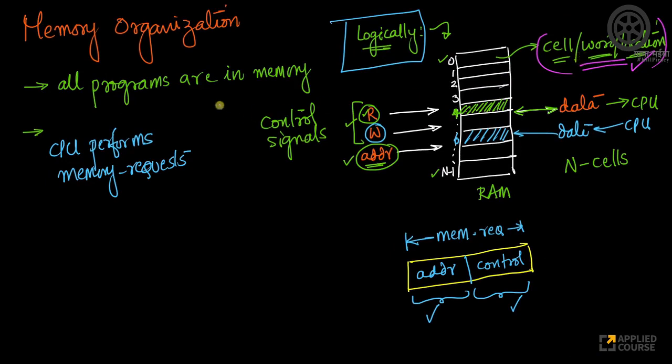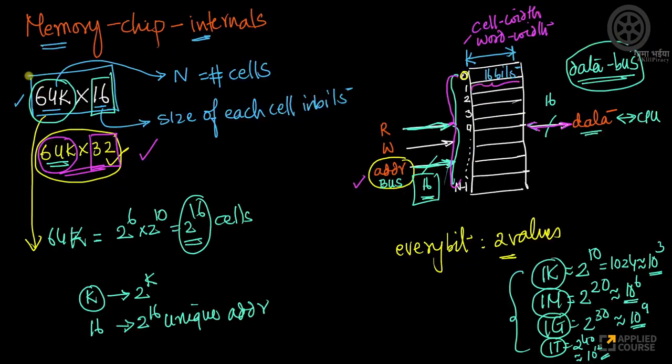So now I hope you understood how we actually address memory. Given this configuration of memory, we need to understand how many address bits there are, what the size of the data bus is, and how many locations there are. Oftentimes in practice, instead of having 2 wires for read and write, you just have 1 wire on many chips.